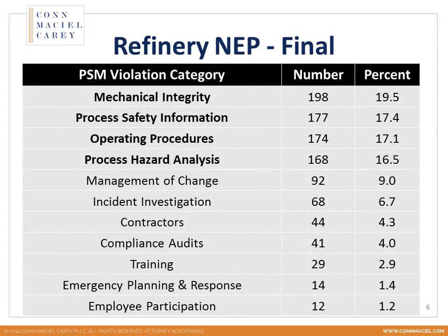But among PSM itself, which obviously was the most frequently cited of all the standards because it was an emphasis on PSM, these were the sub-elements of the PSM standard that were most frequently cited. And sitting right at the top, at about 20% of the total violations issued under the program, were mechanical integrity related. And we'll talk about, in the chemical facilities NEP, a breakdown within that category of what specifically OSHA was finding and citing in terms of mechanical integrity.